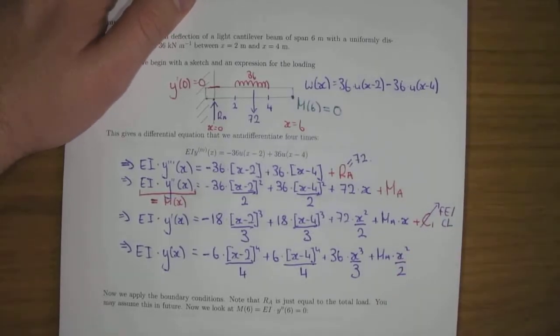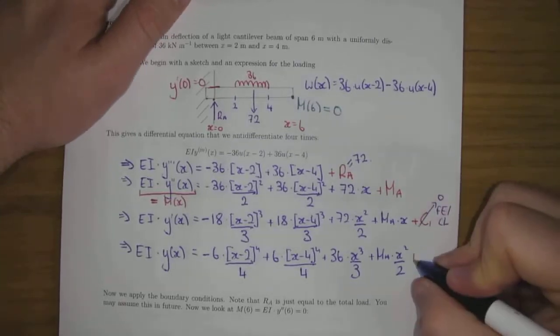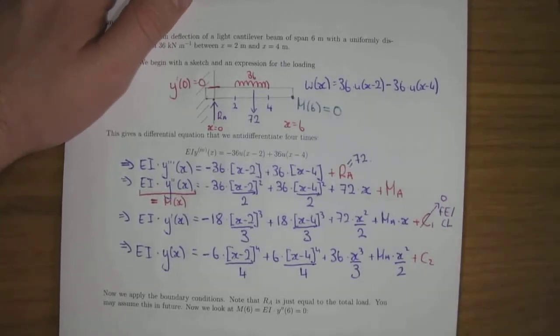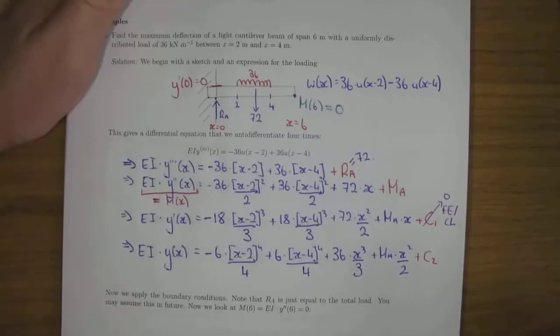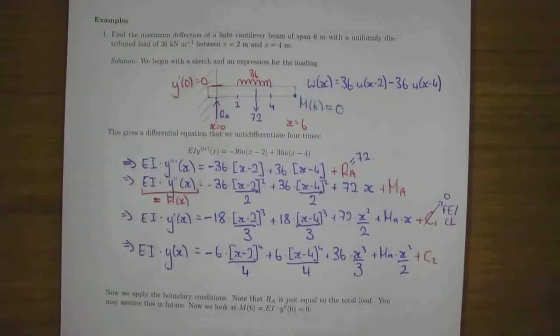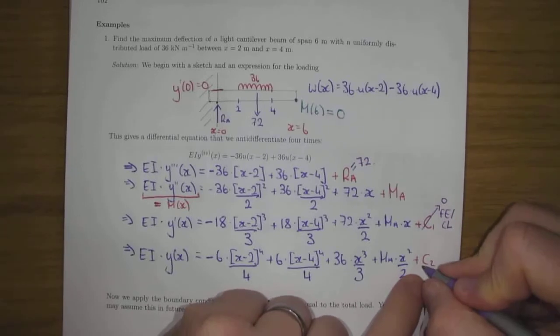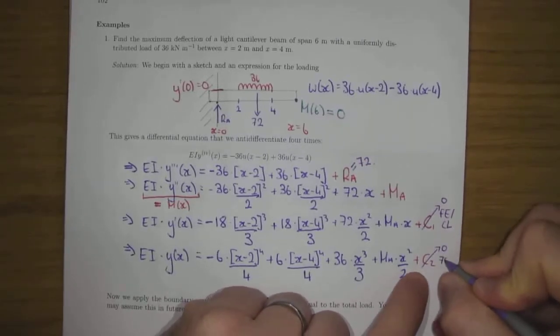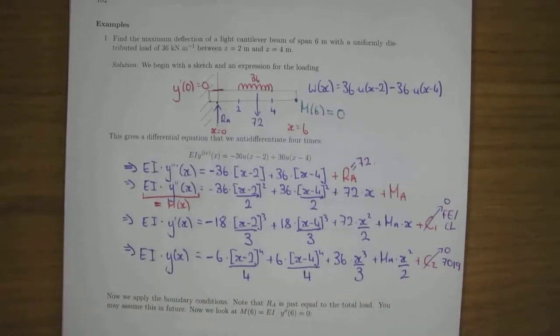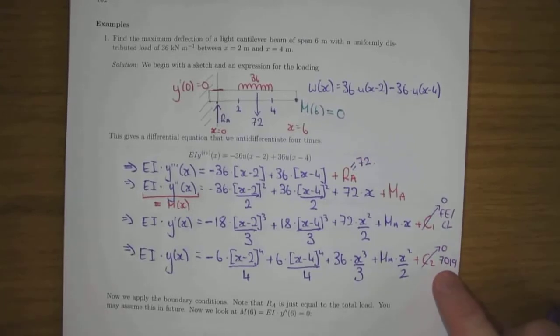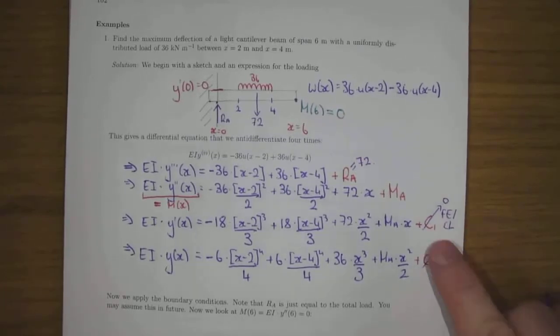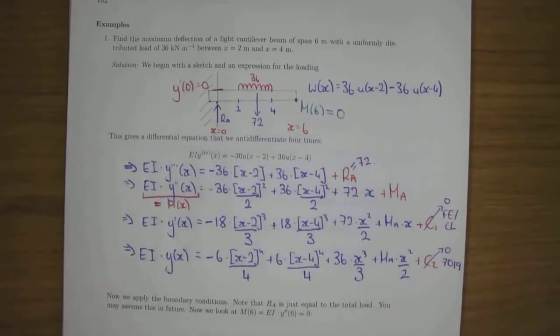Now the C1 is gone, as in it's 0. I'll put in the other constant. I think it's good practice to always put it in, because I actually see students who are trying to be clever here and leave things out. And eventually what might happen is they start leaving out the R and the MA. Bad news, fam. So in this module, C2 is always 0. C1 is only 0 for fixed ends and cantilevers.